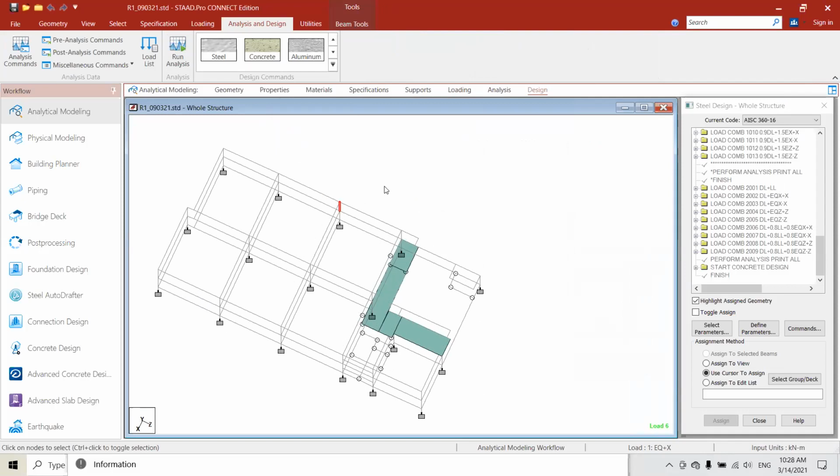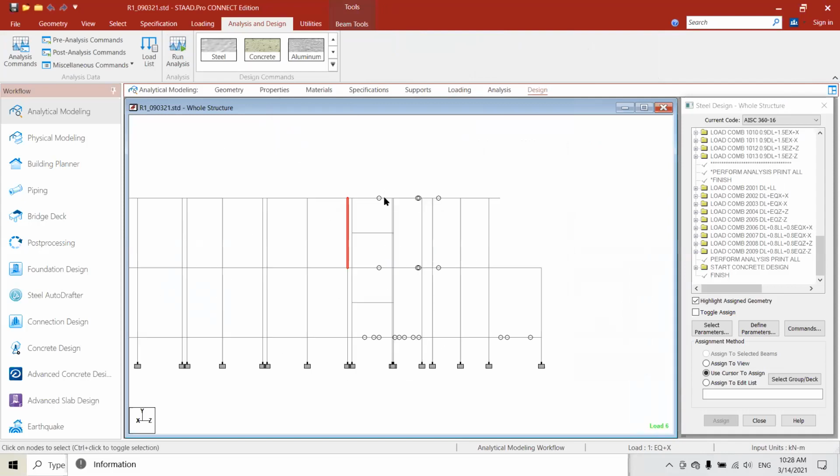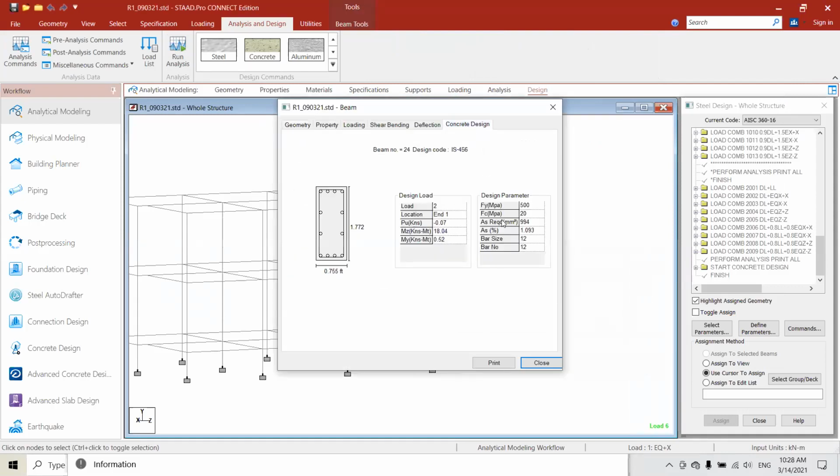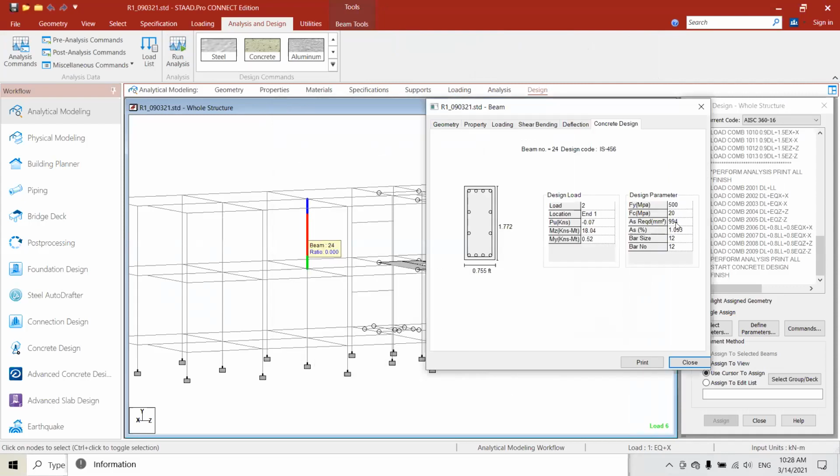Like this is our column. I will click on the column two times. So I will get the reinforcement required as 994 mm² directly from the design part. But now we need to find out the number of bars. STAAD.Pro also gives the number of bars required at this section, bar numbers and bar diameter. But what happened here, if you click here, then second, then we can get 1037. So the same reinforcement is here. You can see the requirement is different, but the reinforcement is the same.